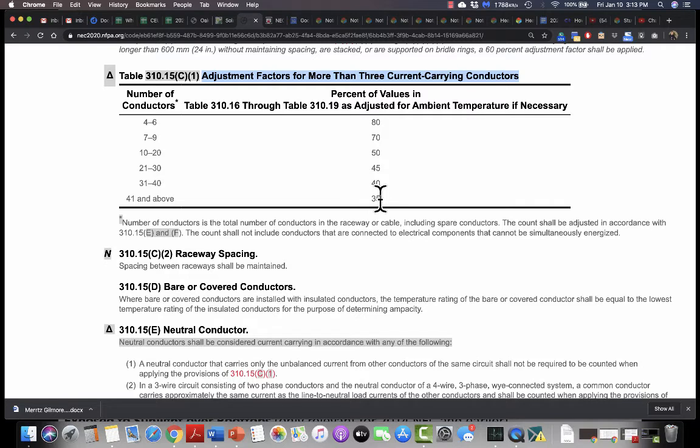And a benefit of using multiple conduits is it's easier to work with smaller conduits. You don't have to have these big conduit benders that are not powered by muscle. You have to get something that is mechanically powered to bend big enough conduit. And another thing is if you bring all your conductors further along, then you can check different things and turn things off, say downstairs or closer to an inverter, if you're on the DC side, or if you're on the AC side, just closer to where your power is going if you're using smaller conductors.